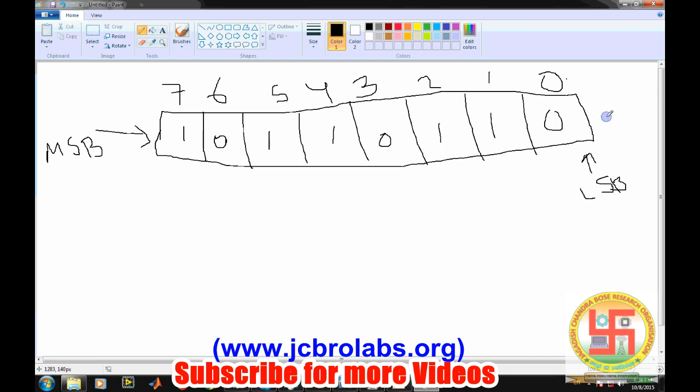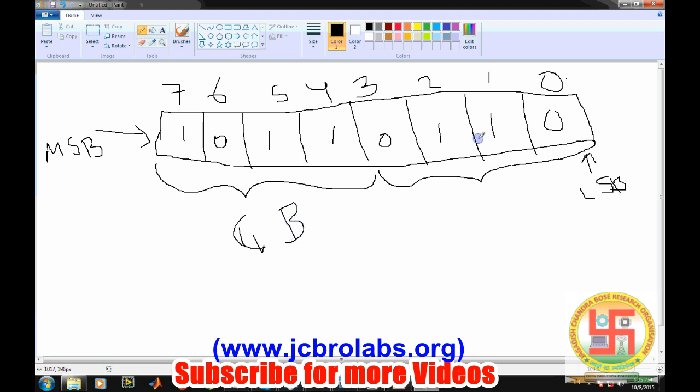Most of the time we will be writing in hexadecimal format, whether it is data or a memory address. So it is mandatory to understand how this works. If we have a register with this much data and want to convert it into hex, just make groups of 4 bits, and this becomes 8, 10, and 11. So 11 is B, and the other group is 6. So this number is B6 in hexadecimal. Think about it as a memory location now. This memory location could be RAM, ROM, or anything else.